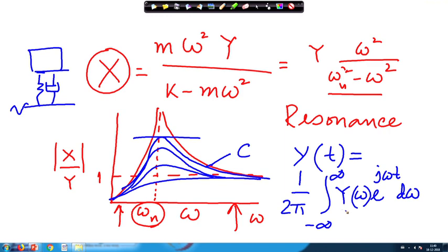In this form, y(omega) is the Fourier transform of the function y(t). So, if the system is linear, and we have already considered the harmonic response, then using the principle of superposition, we can always find out the response due to any arbitrary loading, so far as this is continuous.